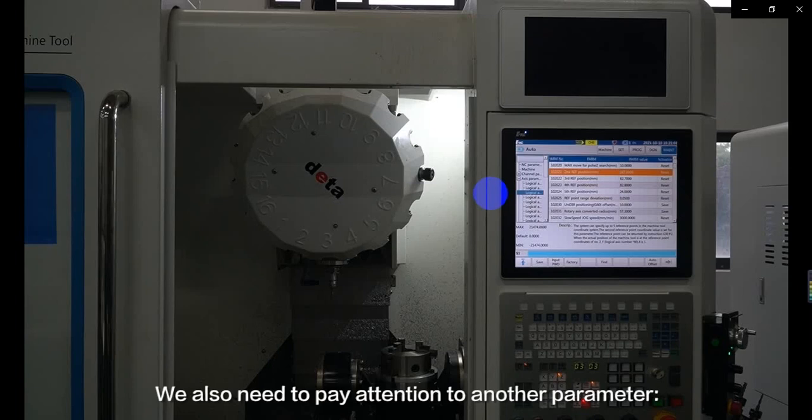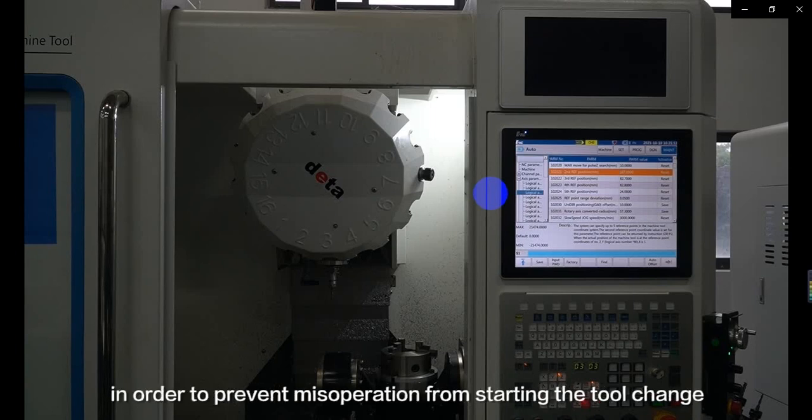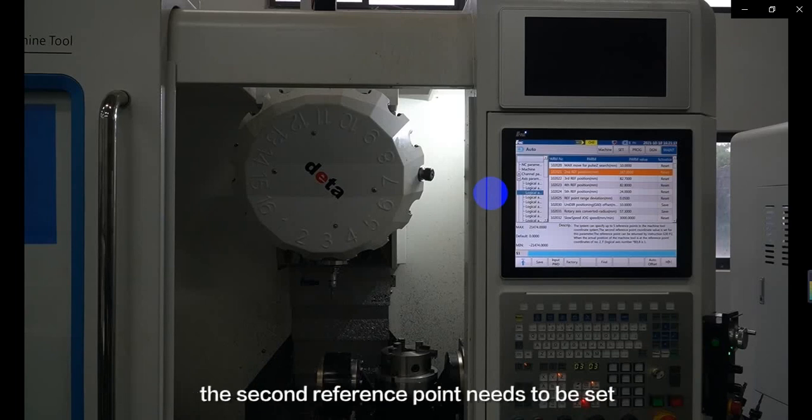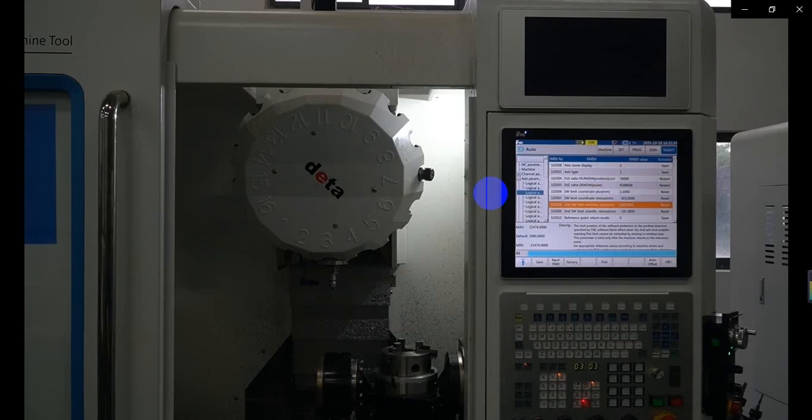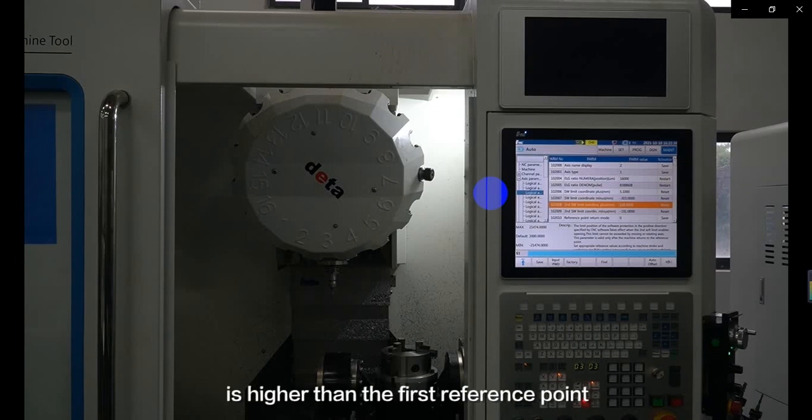We also need to pay attention to another parameter, the second limit, because during the use of the tool magazine, in order to prevent misoperation from starting the tool change, the second reference point needs to be set. Only in the tool change mode, the Z-axis can reach the tool change point. The positive height of the second reference point is higher than the first reference point.